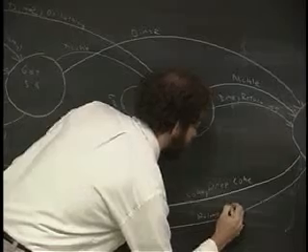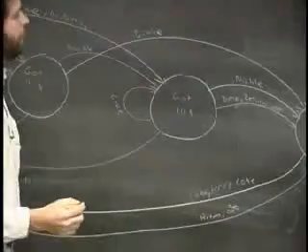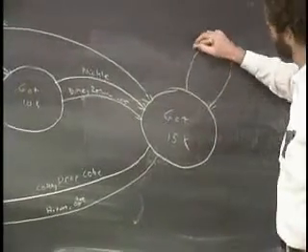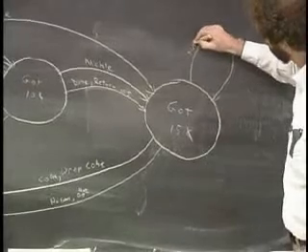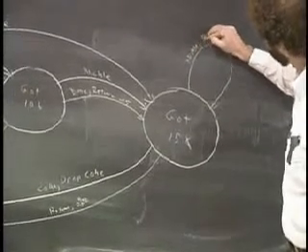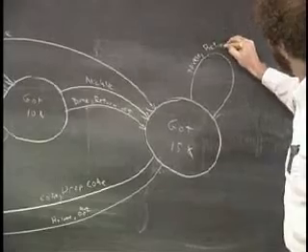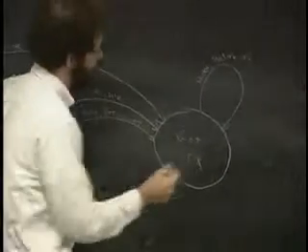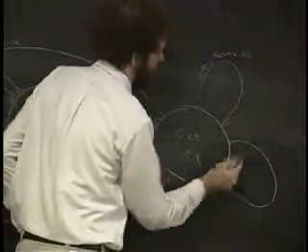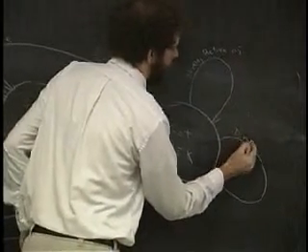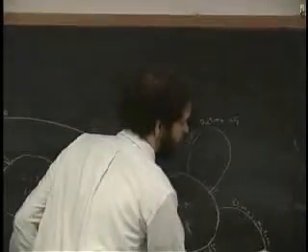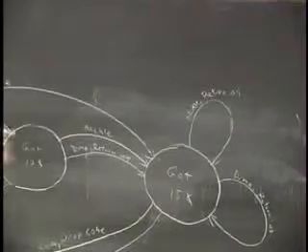And what if they put in another nickel? We want to sort of stay there. So here, nickel. We want to return 0.05. And if they put in a dime, we want to stay in this state. Return 10 cents. And there you have a state diagram for a simplified Coke machine.